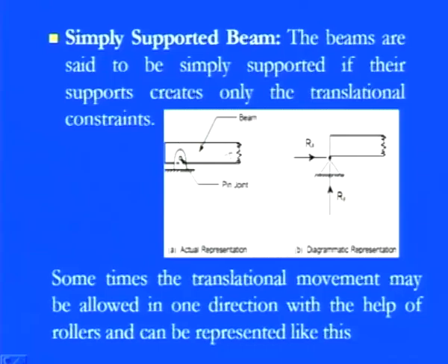and we have a pin joint. The pin joint simply constrains this kind of motion. Whenever a load is applied, the reactions come in the vertical as well as the horizontal direction. You can see how we represent these forces at this pin joint. Under the action of any load, the reaction in the vertical direction is known as the Ry reaction,